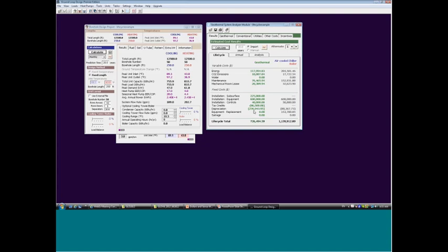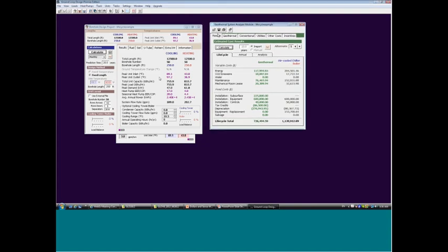Okay, got it. Yeah, Mike. No, Adam, no problem. Just so, what do you mean by alternate in that question? I think you mean alternate design here, right? So I'm going to assume, Adam, that you mean that if you change your loop field design here, can you re-import it to compare? Yes, you can, and I'll show you again how to do that. Right now, my design is 250 feet deep per borehole. I say, what happens if it's 280 feet?